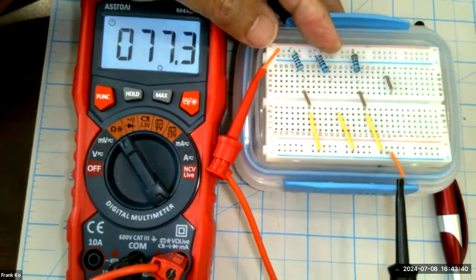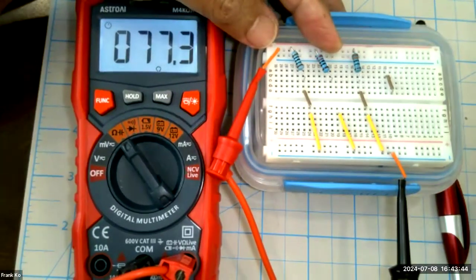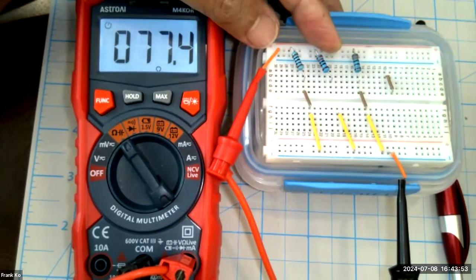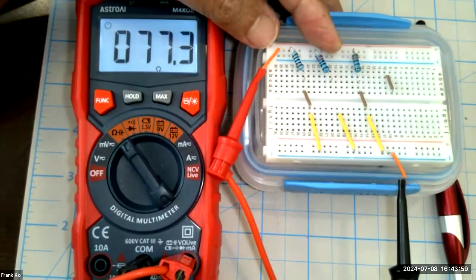What's your journal say? Your journal says, or should say, 76.74 ohms. And is this measurement pretty darn good, pretty darn close to 76.74 ohms, 77 again, given the tolerances of the resistors and some stray ohms that are on the board by virtue of the jumper wires. We're dancing the happy dance.